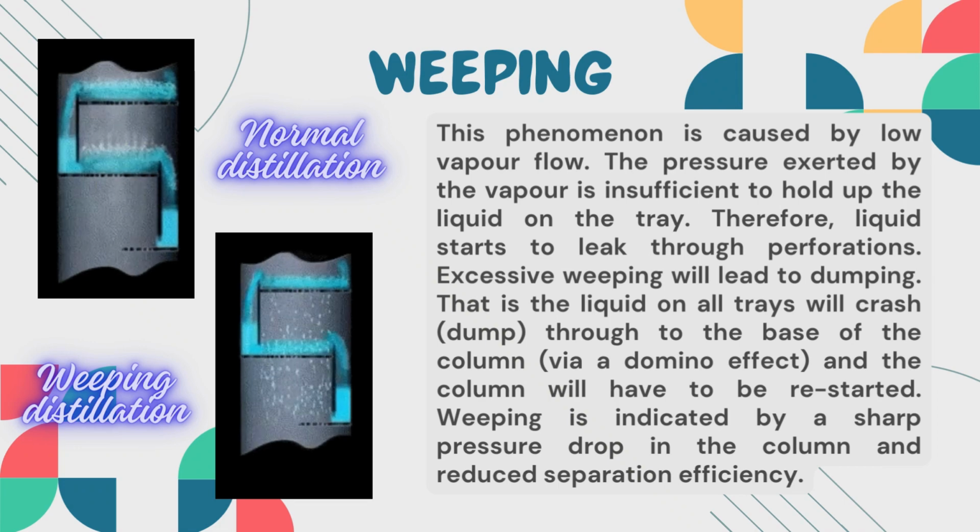So guys, to summarize in simple words, you all know that distillation is a process which works on the principle of vapor-liquid contact. The better the vapor-liquid contact, the more separation will be achieved. And guys, weeping is a problem which is related to this vapor-liquid contact. Guys, weeping is a phenomenon where the vapor pressure is low in the column, due to which the liquid which is held in the trays comes down, due to the low vapor flow rate, and drops onto the next tray and disrupts the vapor-liquid contact, and this leads to less separation efficiency. Okay guys, so this was in brief about weeping.